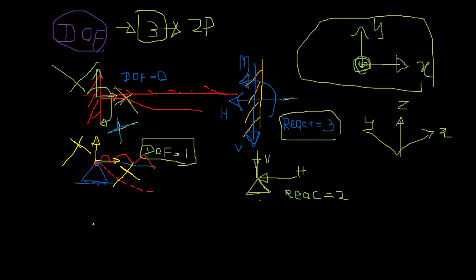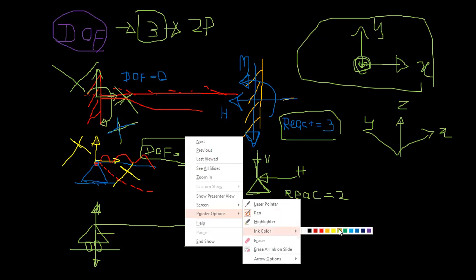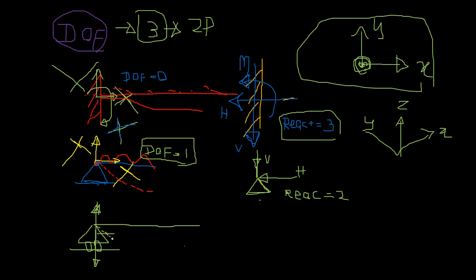If you consider a pin support, right, it is on the ground, so it will not let it move in this way, right, or this way, right? But it can move in this direction, right? And as well if it is loaded, it can rotate as well, right?